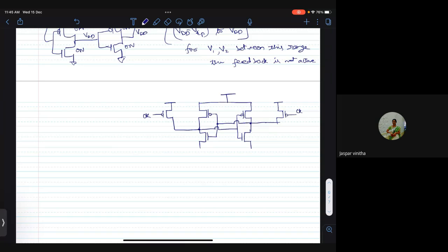Okay, so that is established. Second thing is when clock is 0, outputs are pre-charged to VDD. When clock is 1, that's when I should start trying to take a decision of the inverters based on the inputs. So for that, inputs are connected